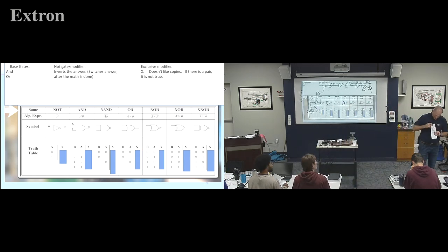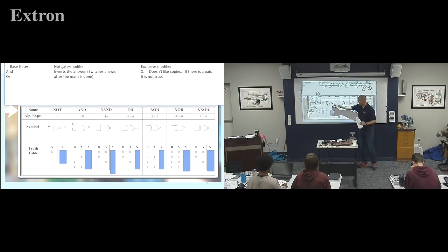Alright, this one here, what he was pointing out is it's very much curved, which tells us OR gate, but they didn't follow our, it's a bad drawing. The nose of it is kind of a funny shape. The nose of it looks like an AND gate, but the back side looks like an OR gate. So whoever drew this thing didn't do us any favors. It is in fact the OR, because you're looking at the curve on the backside. So make sure you're looking at the curve on the backside. So they're OR. I'm gonna have to double check online now and see where he got those drawings from.